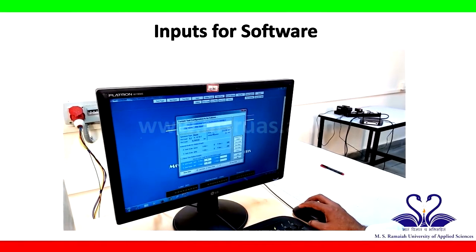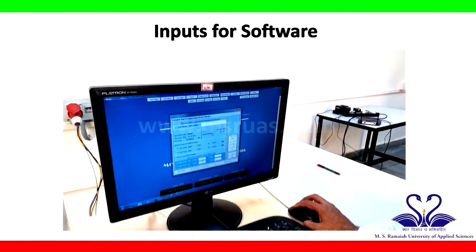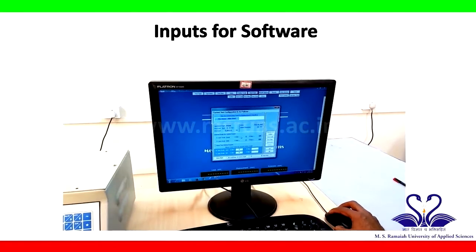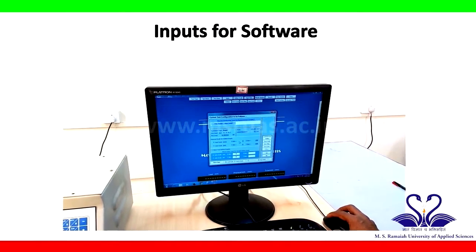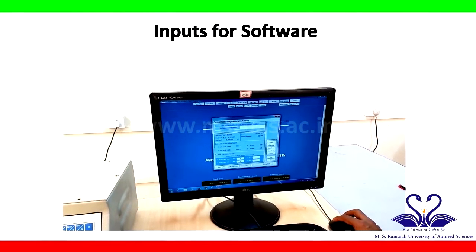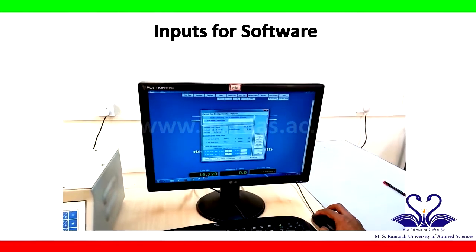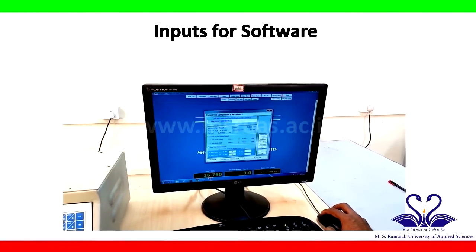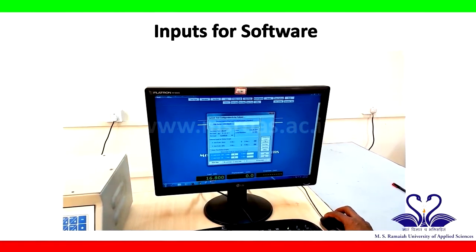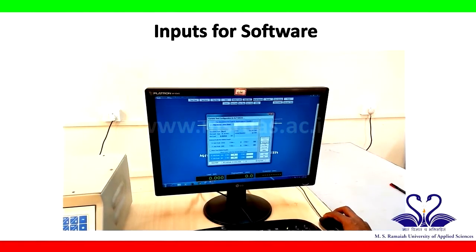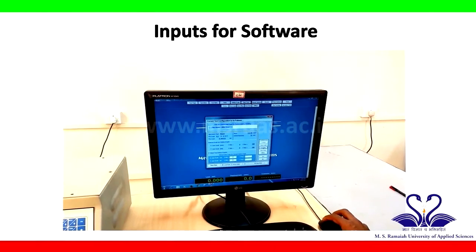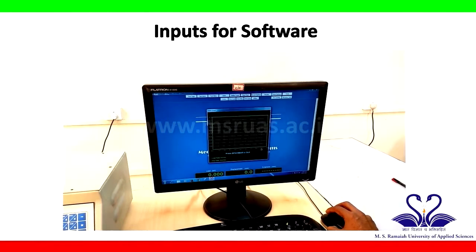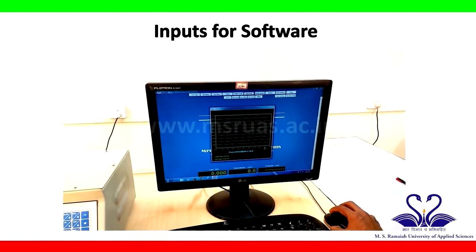It has calculated the area, initial diameter, and here we have fixed the scale for x-axis and y-axis. Now we have to tell online the data from the decoder is transferred onto the software. Before starting the test, we have to make zero load, zero displacement, and then say yes. It will go to the graph mode.